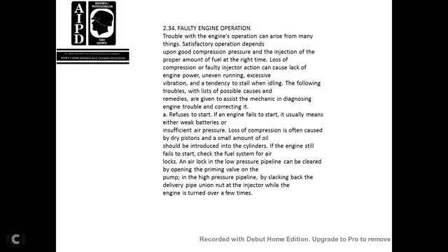If the engine fails to start, it usually means either weak batteries or insufficient air pressure. The loss of compression is often due to a dry piston, so a small amount of oil should be introduced into the cylinders. If the engine still fails to start, check the fuel system for air locks. An airlock in the low pressure pipe can be cleared by opening the prime valve of the pump. In the high pressure pipeline, slacken the delivery pipe union nut at the injector while the engine is turned over a few times.